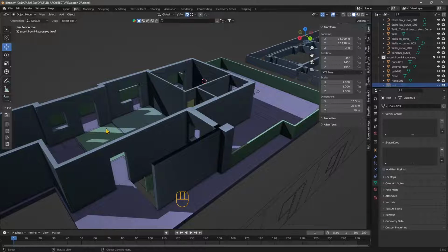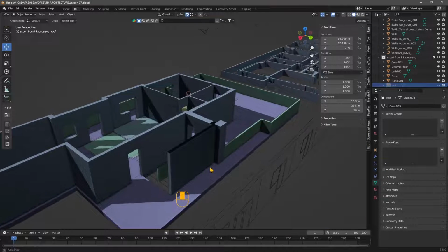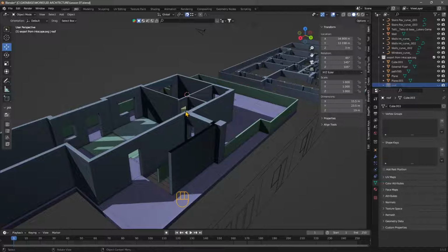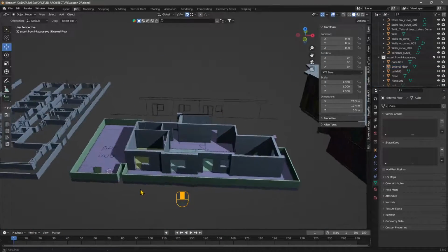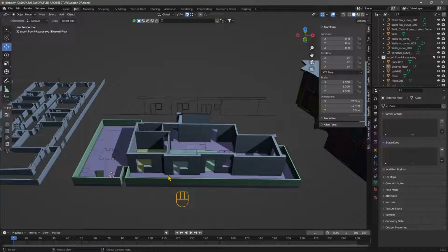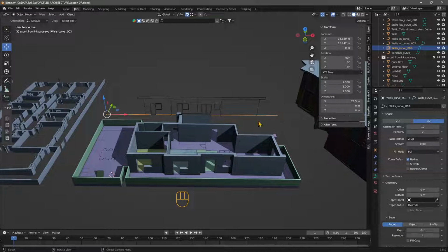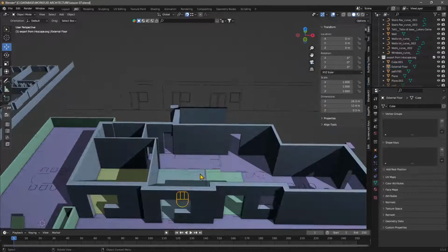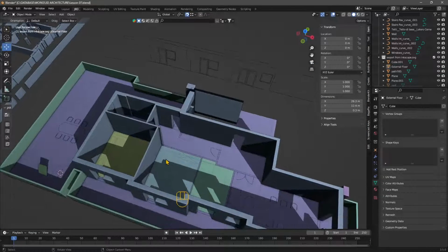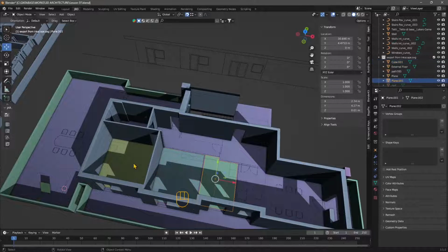To do this, we can actually also use the booleans, but we need to be really precise if you don't want oblique or strange lines and you want to keep everything straight, horizontal and vertical. You can also see here that I've created floors. So we can create floors using the CAD file that we have, just as well as we created the rest of the building. But you can also generate the floors directly right here by using the polygonal modeling. And you can see here I created some internal and external floors.